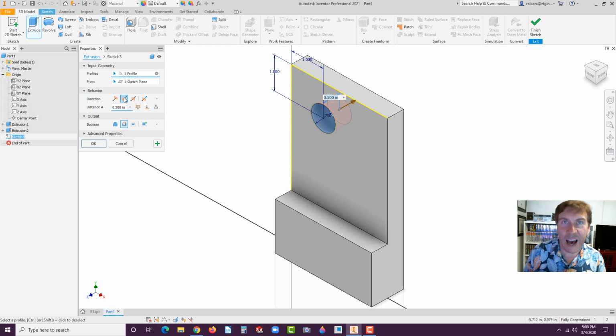There's some AI built in here, artificial intelligence, that knows it had a volume behind it. So you wouldn't typically want to extrude volume over volume. So it knew to just remove the material, which is really nice. But note it doesn't always do that, depending upon the conditions behind it. So just always double check, make sure it looks like a hole.